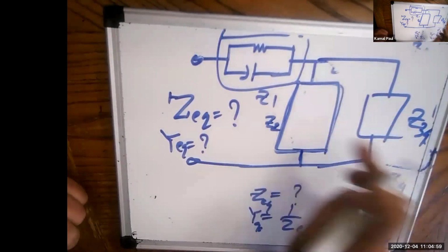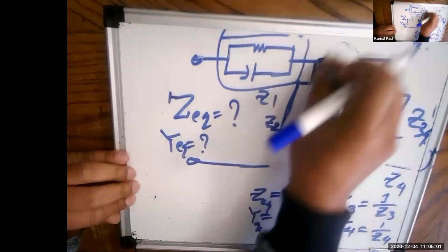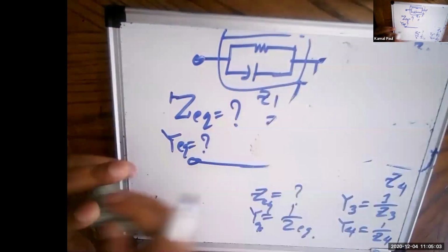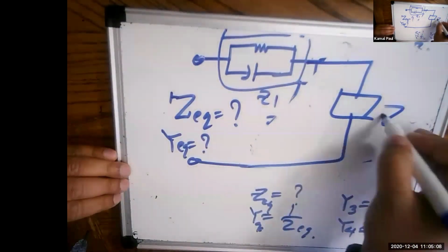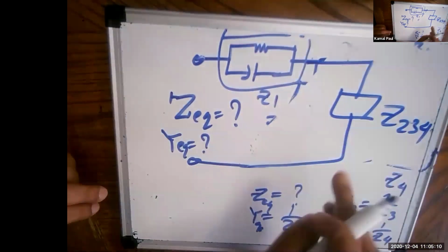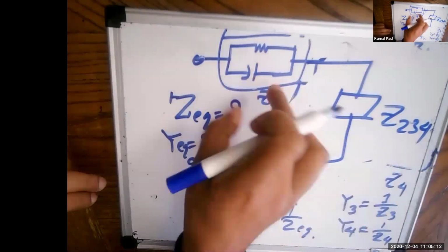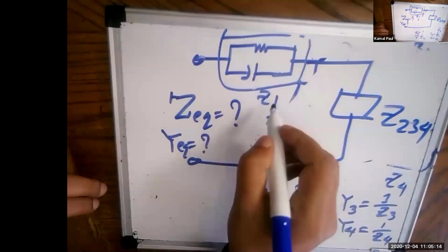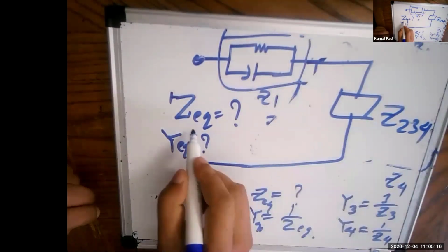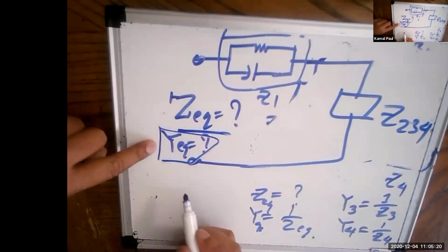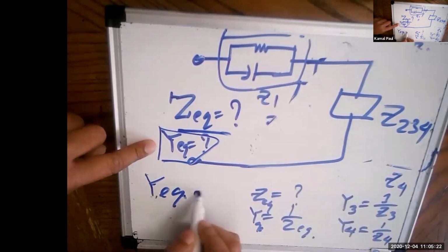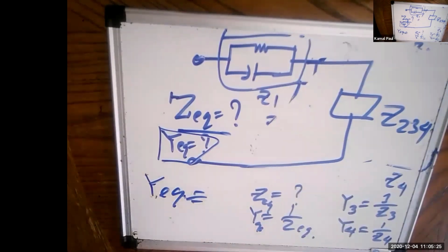Now once you get these two in parallel, make another circuit, maybe replace these two into here, G total, G2, 3, 4, and then this is in series with this one, this value, like this G1. Now you get the equivalent total and then convert it into Y equivalent, even if it is asked to find out Y equivalent. Like this is the easiest way I know.